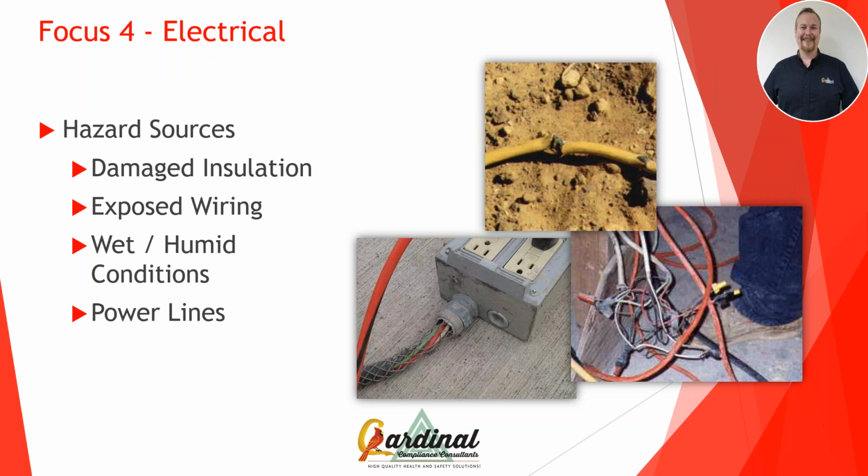You know, it's a given that you're going to inspect your tools prior to the shift, before you use them. But reality, that's perfect world. Even though we tell people to inspect their tools, again, back to relying on people to make good decisions consistently. So plenty of people are not always going to make that good decision. They're not going to inspect their tools, their work area, and that's where we have damaged insulation or exposed wire that's just not noticed.